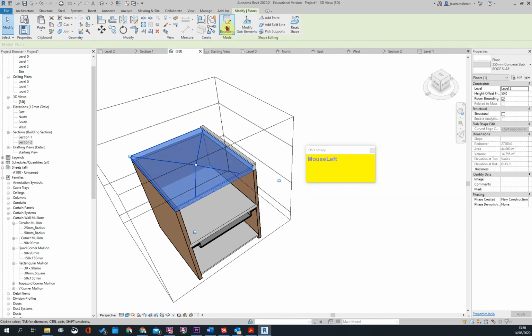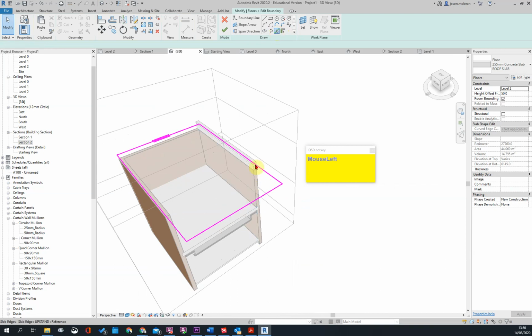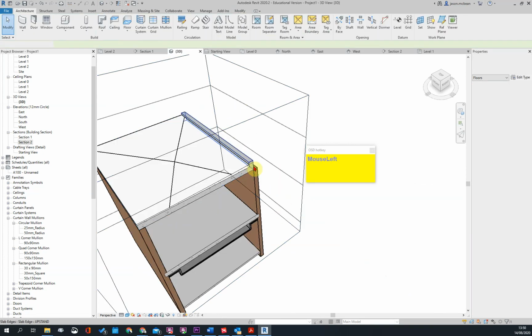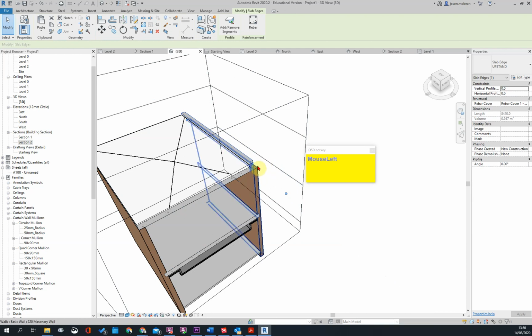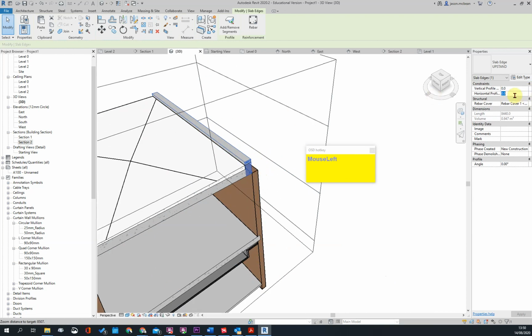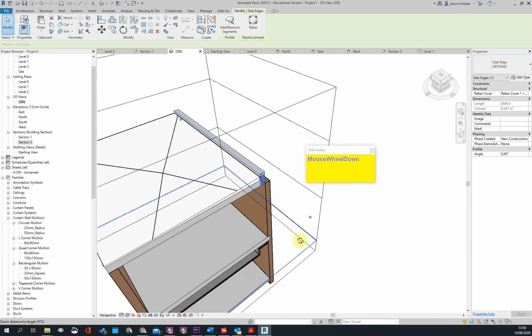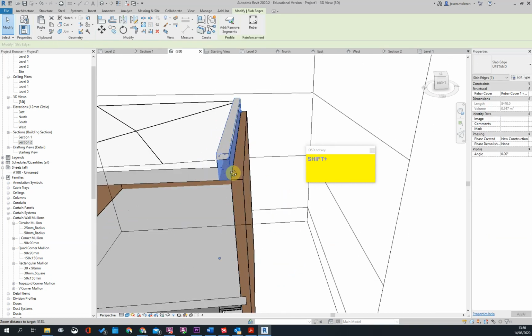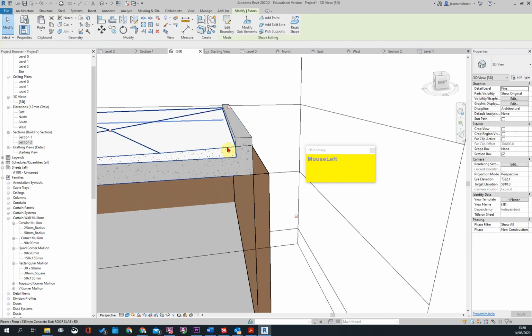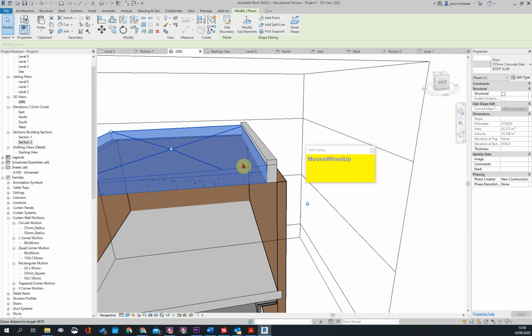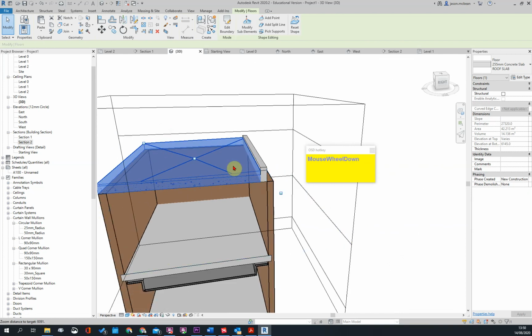Okay, so here we're going to say edit boundary, and I'm just going to pick the inside of the wall, for example. Align, use my align tool. Doesn't matter at all. Okay, yep. And I'm going to say offset. So you can use an offset here to export it to the exterior side. But you'll just have to bear this in mind. This does get tricky, and having this material. What I usually do is I make another floor that sits on top of here, which then adjusts. So that's how I get around it.